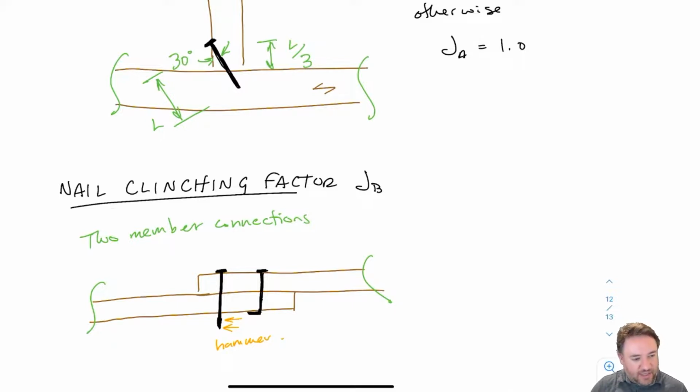and that makes the lateral strength higher, because when we talked about the rope effect, if I want to bend this nail as it goes down, it also has to come in, right? As this thing bends down, the point goes down and also comes in, because it's moving on the arc of a circle.